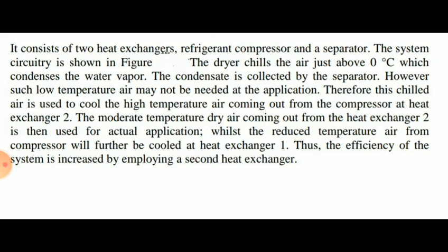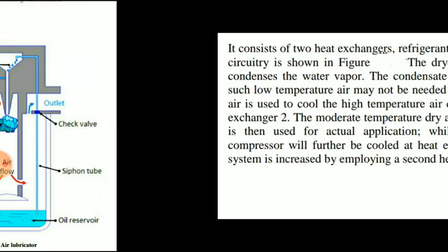The moderate temperature dry air coming out of heat exchanger 2 is then used for the actual application, while the reduced temperature air from the compressor will further be cooled at heat exchanger 1. Thus, the efficiency of the system is increased by employing the second heat exchanger.